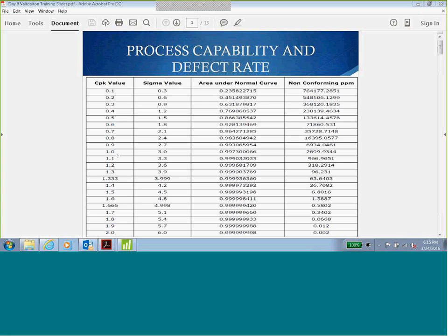It's very, very difficult to get a CPK value of 1.33 in a real scenario. Actually, the industry or the people are going to be targeting for greater than 1, or at least greater than 0.8 or 0.7, sometimes depending upon the risk involved here. But you should want your CPK value to be greater than 1. So remember that. Industry standard is 1.33.